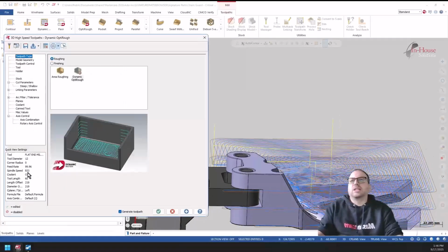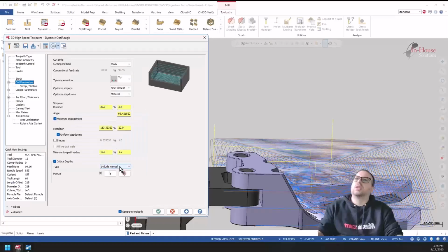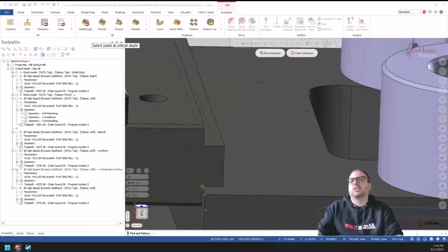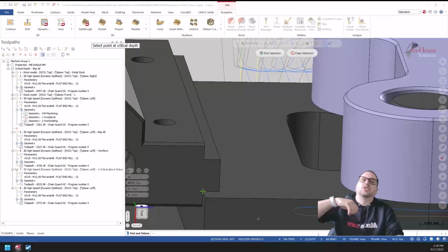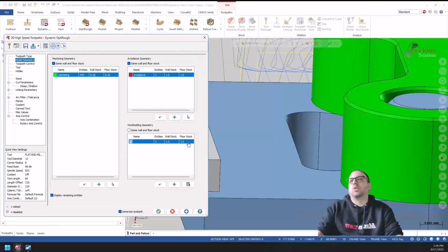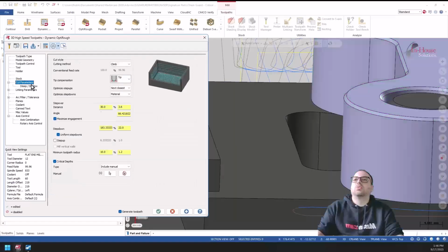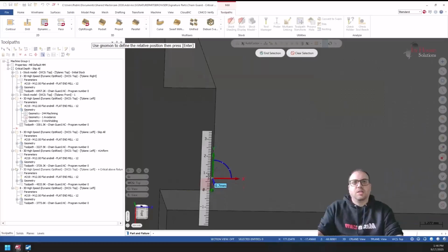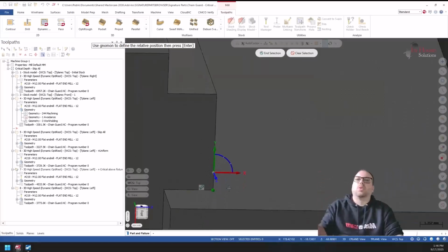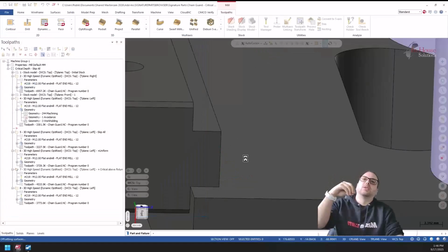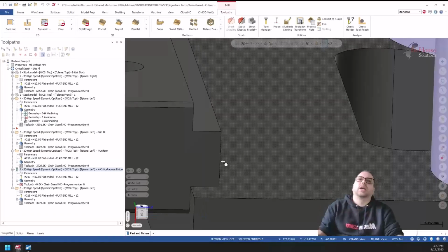So in this example, in my cut parameters, I use include manuals. If I select this, you can see that this point was selected. This is all right, but the problem is that because there's a collision tolerance on this, it's part of my work holding, and I have 1 mil of tolerance, it cannot actually create the pass that I need. So instead of using that point, I can just shift click here and make sure I'm a bit above the 1 mil tolerance. It will then force the toolpath to make a depth cut at that specific height.